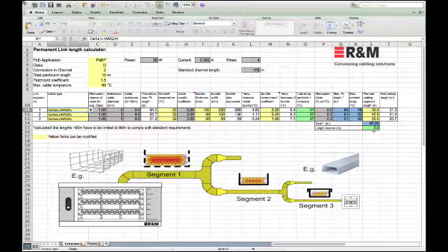So you're all in the green here in the link lengths, and you are in the green on your total temperature on your cable. This is a valid planning, and this probably represents what you have today. If you just work with PoE Plus, you don't concern yourself with any planning, and you see that you're probably on the good side.